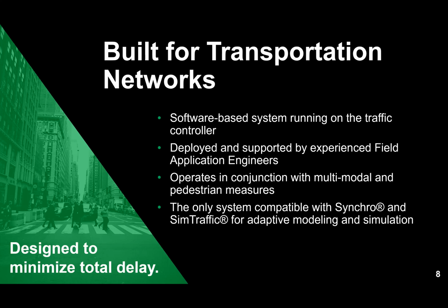And finally, what's unique about our adaptive is that a lot of you may know that Trafficware also has a product called Synchro. And SynchroGreen is the only adaptive system out there that is compatible with Synchro and SimTraffic for adaptive modeling and simulation. If we're able to get Synchro files from that agency, we can run a simulation and give the agency an idea of how much reduction in travel time they may achieve with adaptive running on a particular corridor. And that's very unique to SynchroGreen.